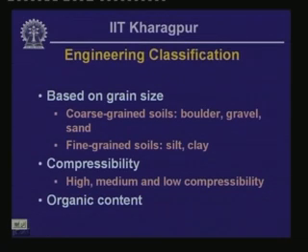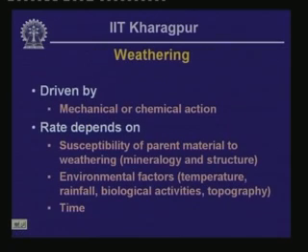Here the classification looks at the grain size distribution mainly, and to some extent it looks at compressibility of the structure and also the organic content of the soil. How the individual classifications of soil will be considered later on in one of the future presentations of this course.